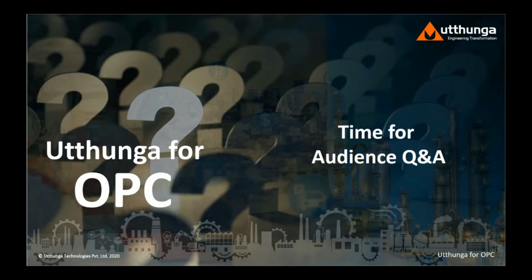On embedded devices, can we integrate web protocols like MQTT? Yes, again, it depends on the use case, what kind of device you are producing. If you are creating a simple IoT connected device, then yes. Or even if you are creating a gateway where OPC UA is used to gather all the data, you can use MQTT for publishing to the cloud. Such gateway devices can also be enabled with them.